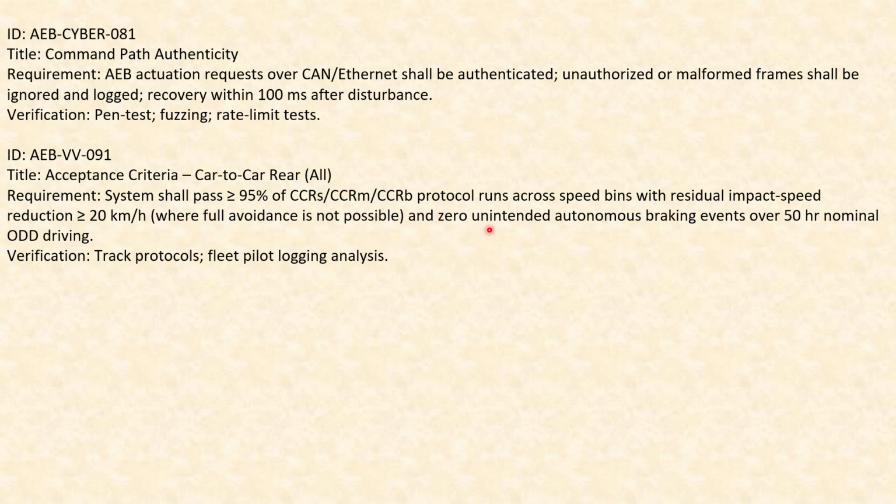And also zero unintended autonomous braking events over 50-hour nominal ODD driving. So across 50 hours of nominal driving, unnecessary autonomous braking must be zero. This is verified on a track protocol, a proving ground, or fleet pilot logging analysis. This is the name of the verification step.